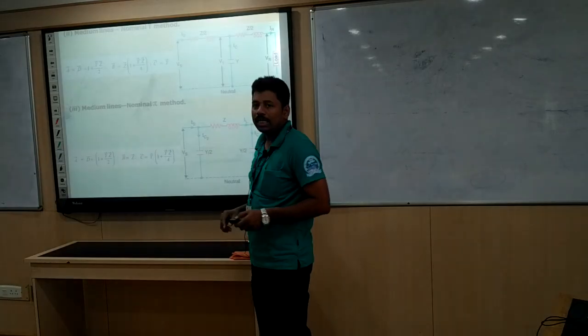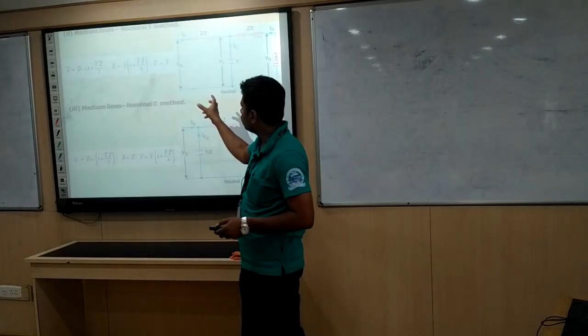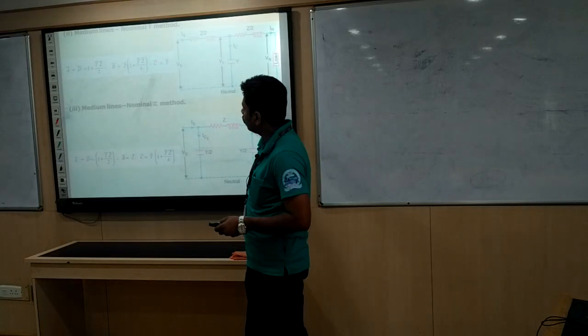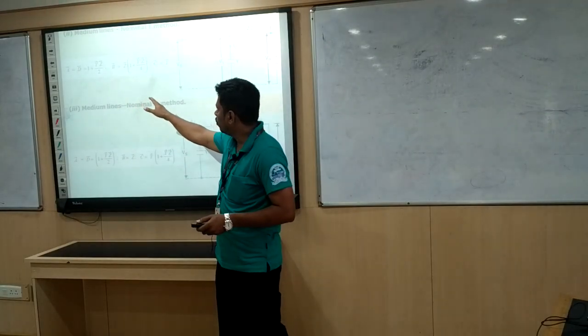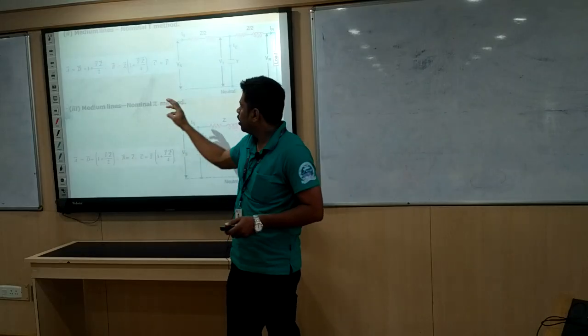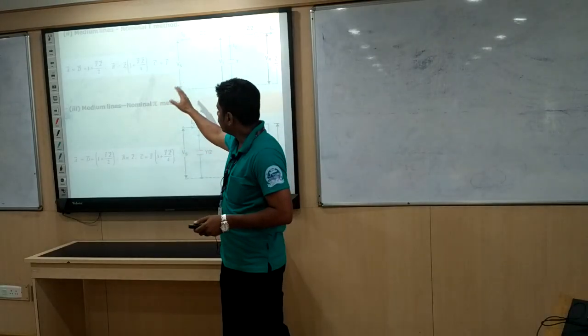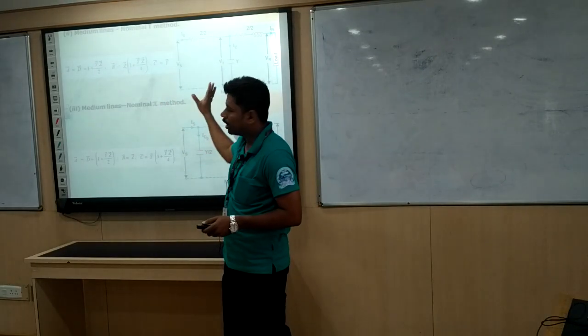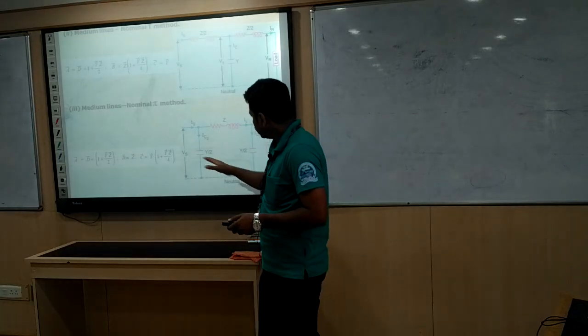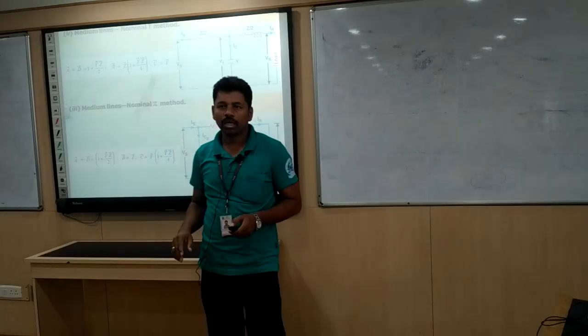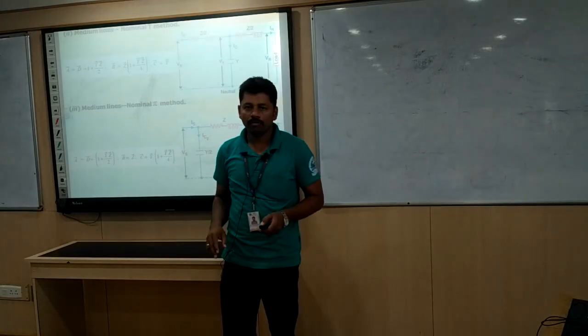And coming to the nominal T method, you know the final expression, this is the equivalent circuit for that. Compare the equations, and there you get A equal to D equal to 1 plus YZ by 2, B equal to Z into 1 plus YZ by 4, and C equal to Y. These are the expressions we have. Then for the nominal pi model, these are the expressions. Once again, using these, we can find the voltage regulation and efficiency.